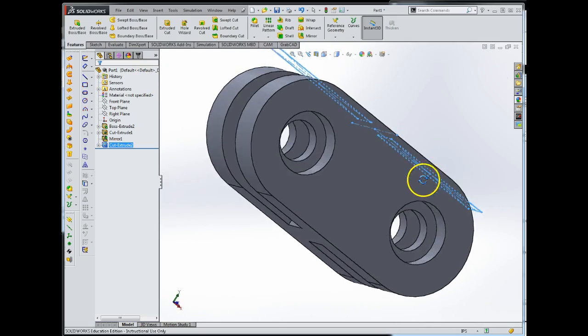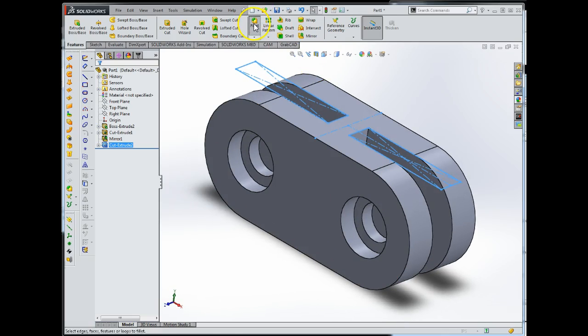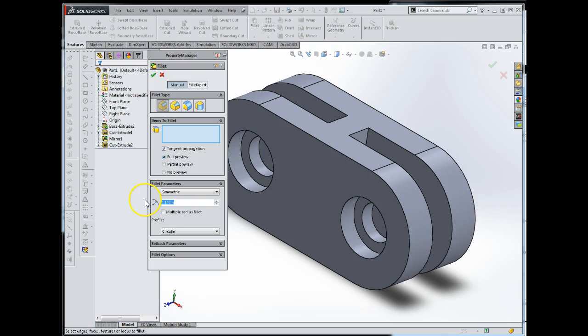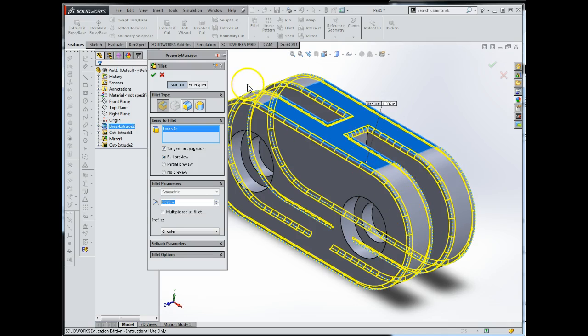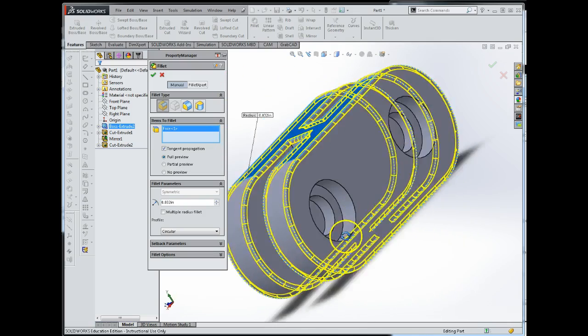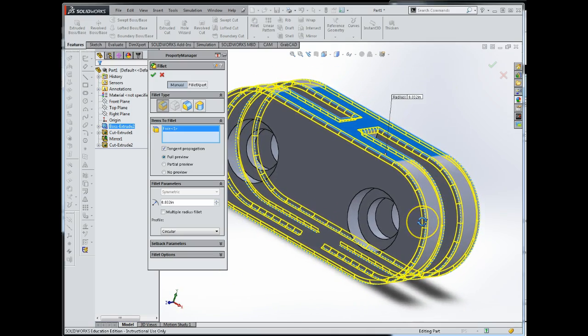And next we're going to add some fillets. Jump up to the fillet command, set our value in at 0.0232, and I'm going to select this surface because I believe this is going to take all of the areas that they're looking for. And notice that it highlighted all of the edges with the exception of the holes, and I can rotate that around and take a peek. And if we take a look at the part there, that's what they're looking for. Hit OK.